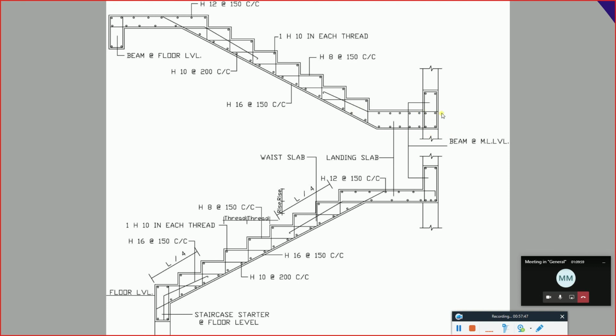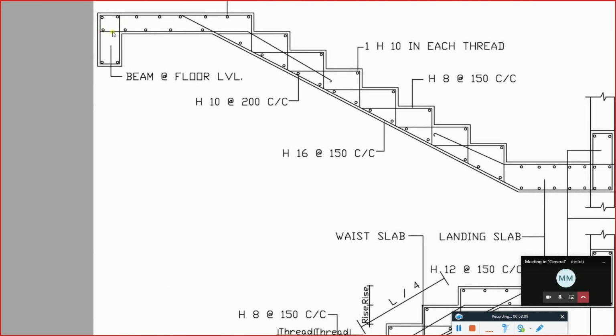So you have one beam on the side, another beam on the side, and then you will have negative bending moment, positive bending moment, and then negative bending moment. Now shift it to the regular staircase, the same bending moment will come. So negative, positive, and then once again negative. Okay. How that is going to be related, you need to understand that this is going to be your